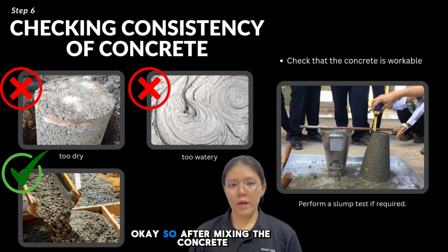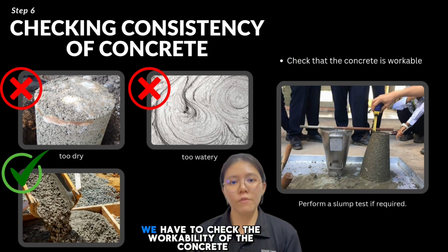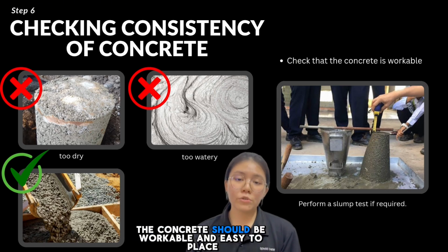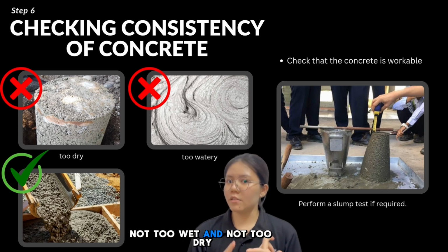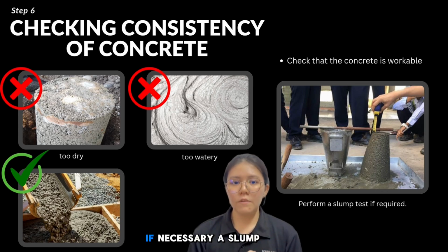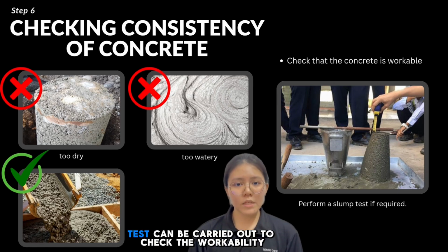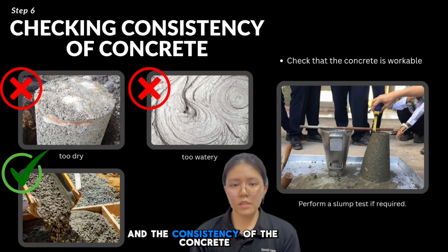After mixing the concrete, we have to check the workability of the concrete. The concrete should be workable and easy to place, not too wet and not too dry. If necessary, a slump test can be carried out to check the workability and the consistency of the concrete.